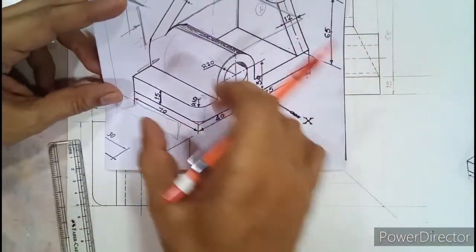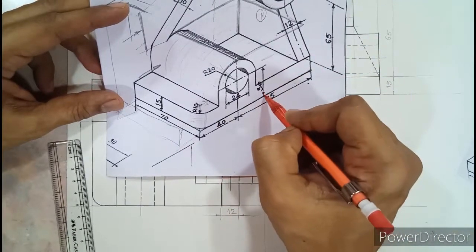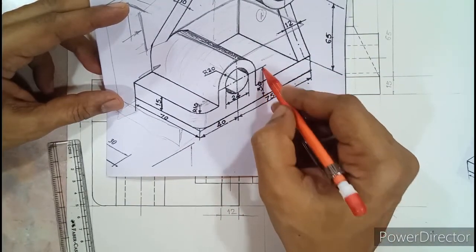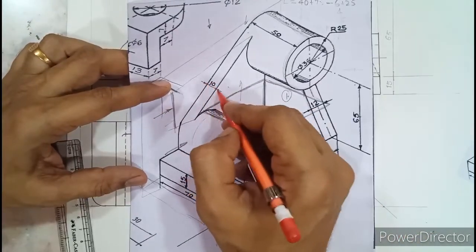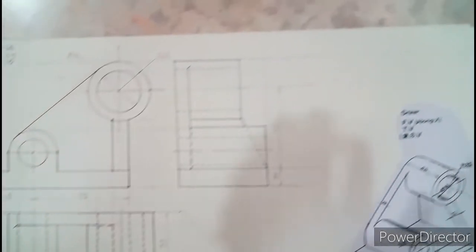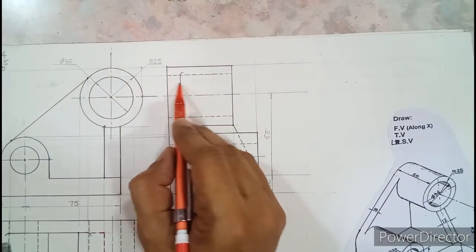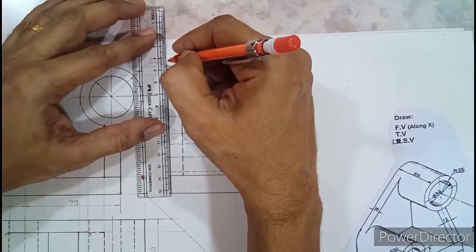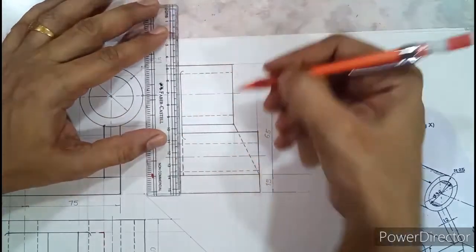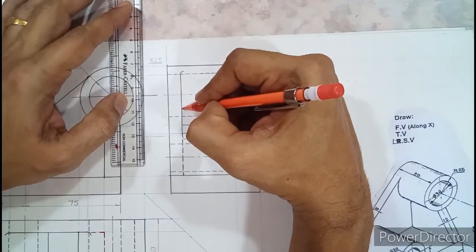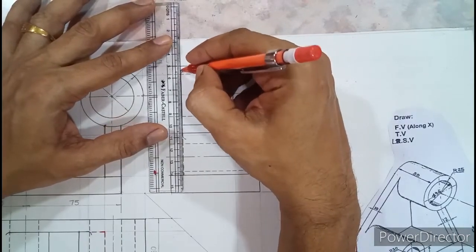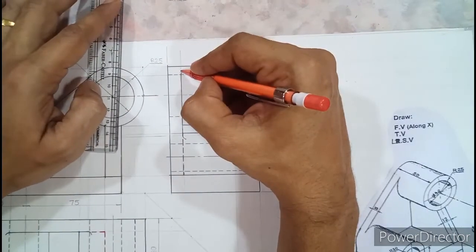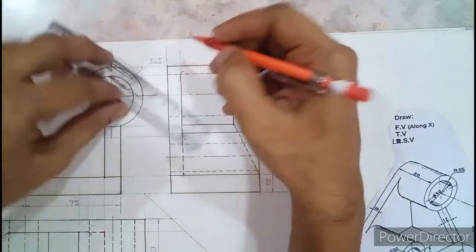What else can be shown over here is this height 30. Okay. Or you can show this thickness 10. So let us see how to show this 10. In the side view, this thickness is 10, isn't it? So from here we can draw a medium dark extension line. When you draw the extension line from here, you need to leave 2 mm gap from inside. The extension line should pass from inside the object.